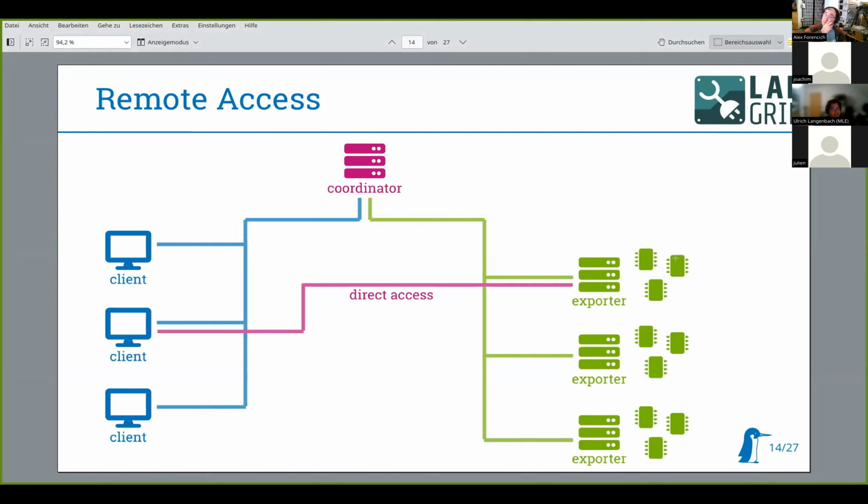And we added some capabilities to upstream LabGrid, although we are running a pretty old version, I guess. We changed JTAG support to get the ability to interactively talk to the FPGA via JTAG. The original support was more: program a bitstream into the flash, reboot. That's okay, but we also want live access to run ILA captures and so on, right? So is that something like you started up the Vivado hardware server or something?